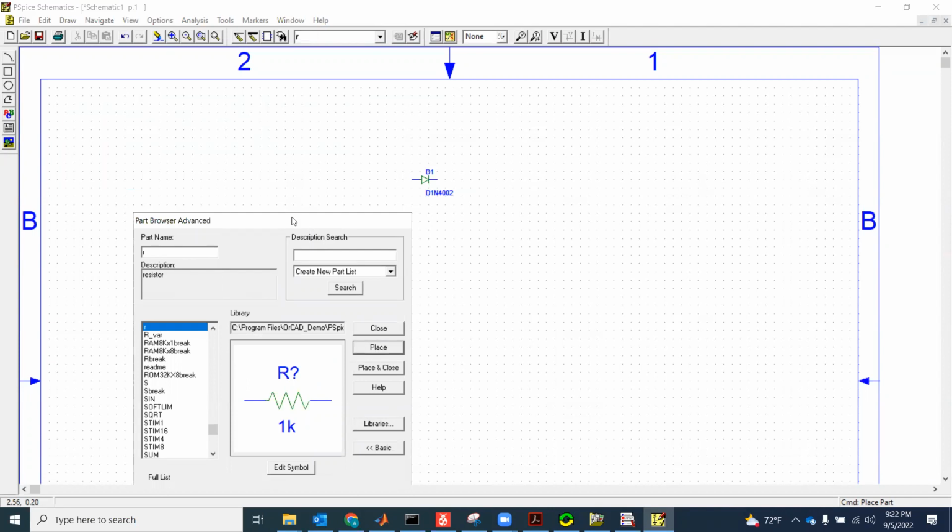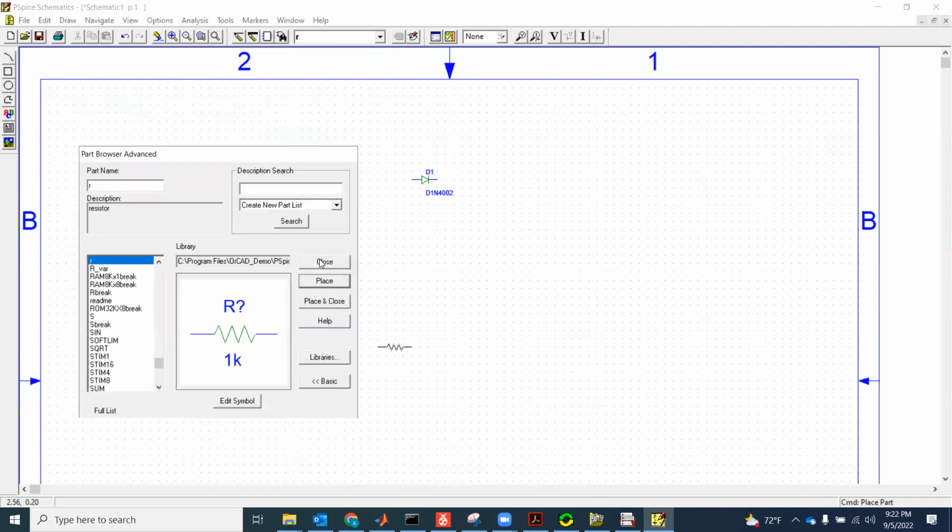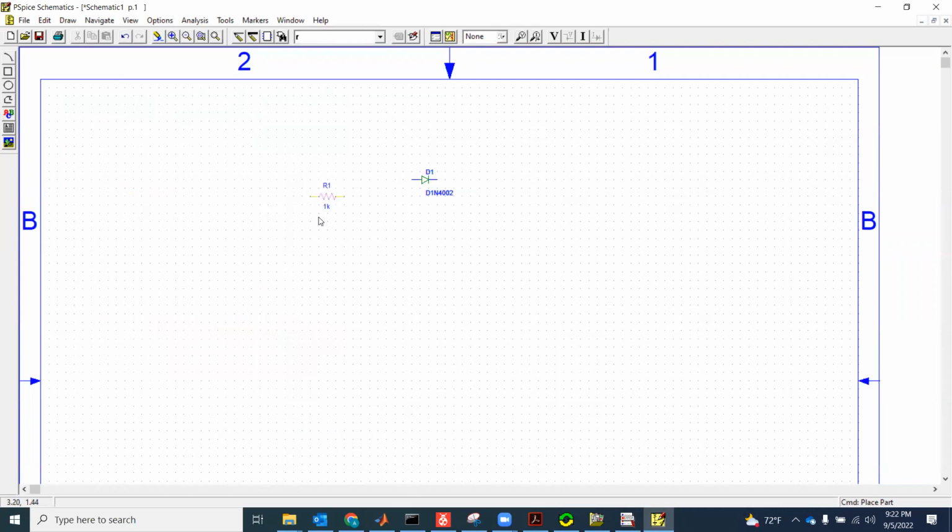Okay, I have to close and then press again. So this is VDC. Yeah, okay. And last thing, for any kind of circuit, guys, you have to add ground because it's going to consider ground as your zero or reference. So let's now arrange the elements and connect them in series.